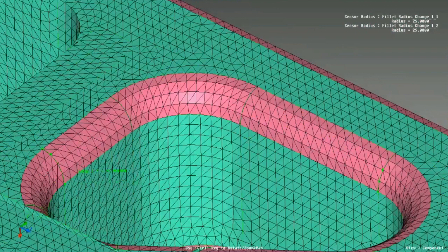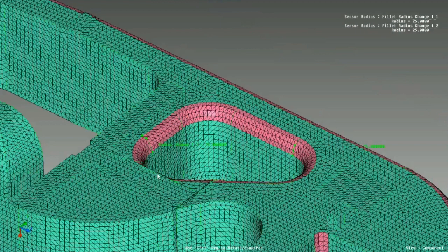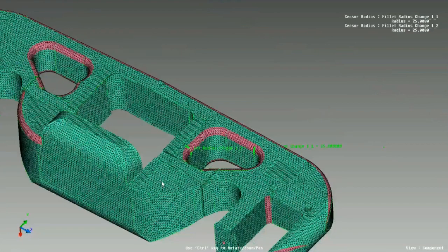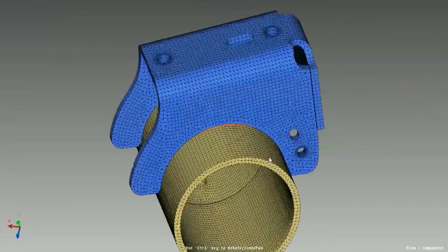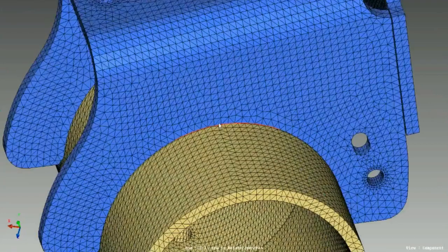Similarly, the user can also create parameters for changing the tube diameter and also rib thicknesses. And the next demo that we'll be seeing is on the seam weld. So where we have thick sheet metals, sometimes they are modeled, instead of shell mesh, even as a tetra mesh.